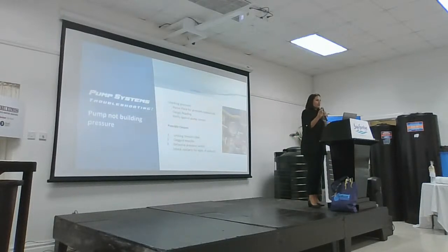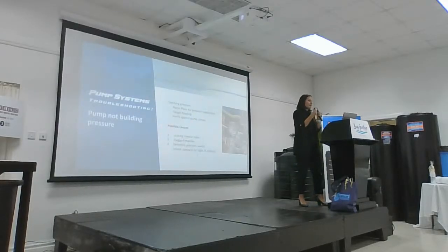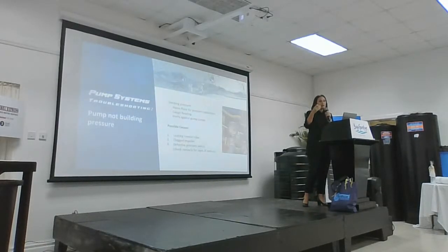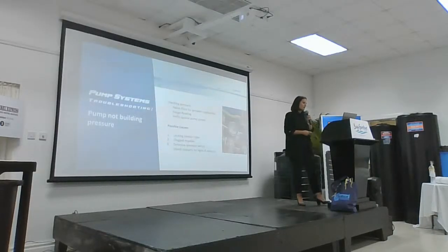You take the gauge reading, you check the nameplate for the pressure capabilities, and you verify against the pump curves. So any discrepancy would be a red flag. The pump is not building pressure.